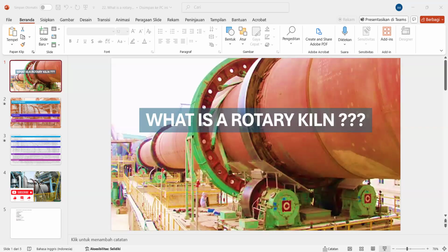Internal heat exchange: heat exchange in the rotary kiln may be by conduction, convection, and radiation, in descending order of efficiency. In low temperature processes and the colder parts of long kilns lacking preheating, the kiln is often fitted with internal heat exchangers to ensure the exchange between the gas and the feed. This might consist of scoops or lifters that lift the feed up through the gas stream, or metallic inserts that heat up in the upper parts of the kiln and impart the heat to the feed as they dip below the surface of the bed.